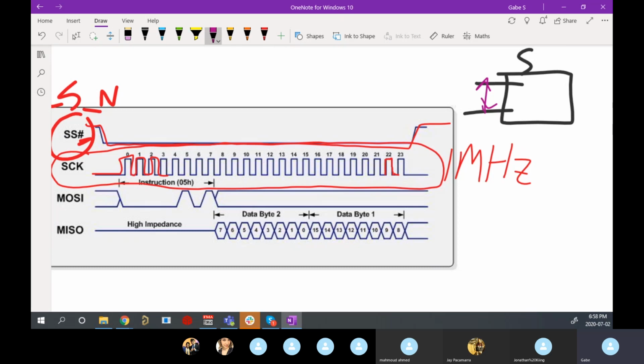Maybe that window is anywhere from like 1 kilohertz, for example, to 20 megahertz. I just made that up. It can be very different for whatever chip you're talking to. Usually they'll give you a window. A lot of times there won't be this bottom side, so you can go as slow as you want. Slower is easier for me. But definitely on the faster side, there will be an upper limit. So you've got to look at your data sheet to make sure you're not going too fast, so that you can make sure that communication actually is received properly by the slave.